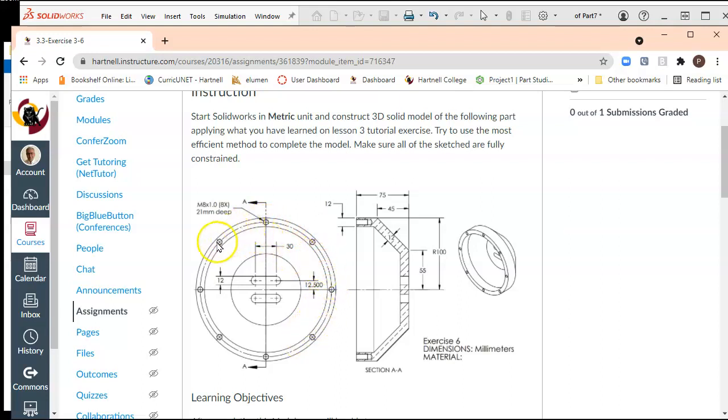They should have had dimension for this, what we call bolt circle, but it's not showing the dimension. But we know for sure this should be exactly in the middle, equal distance. So we know the dimension on this one was 100. So if I go to this one 12, so that would be 6 between, right? 6 between here to here. So if I do the 6 less than 100 would be 94 radius. So if I add 94 dimension, that would be perfectly in the middle and also aligned with this center. So just something to be more accurate there. And let's go to that.